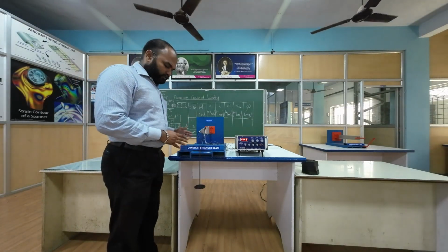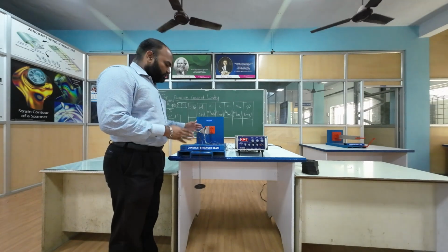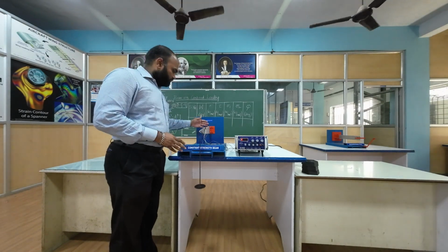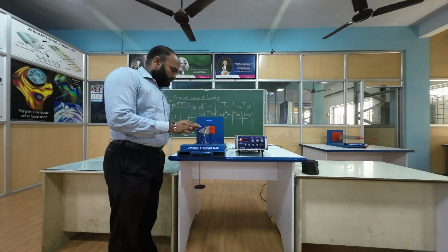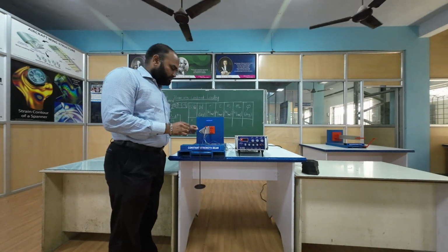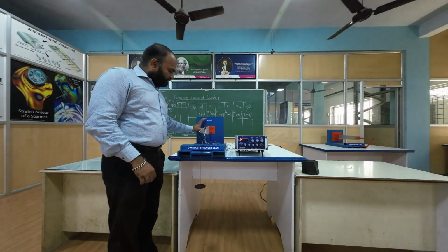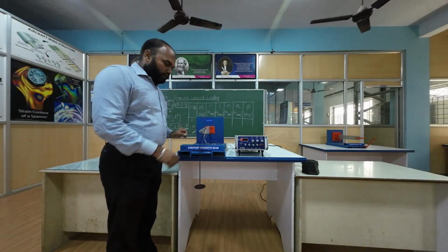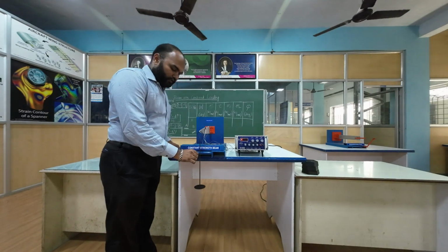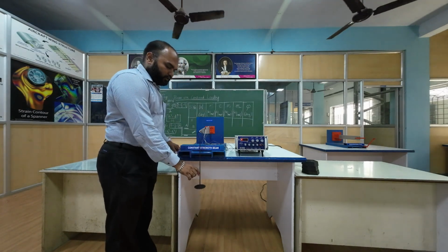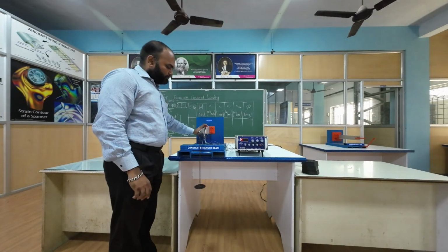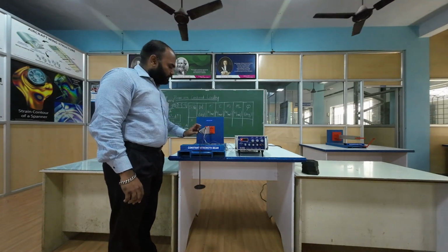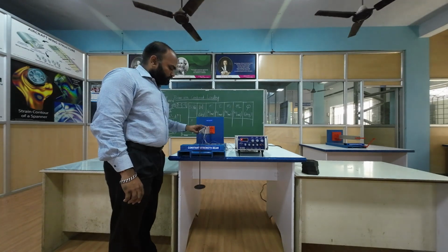We have an experimental setup for a constant strength beam. This is a cantilever beam fixed at one end. The beam is 460 mm in length and 4 mm in thickness. The depth varies from the root to the tip. At the tip we have a weight hanger where we apply loads. For the applied load, we have strain on the beam. We have multiple strain gauges on the beam at locations 1, 2 and 3.